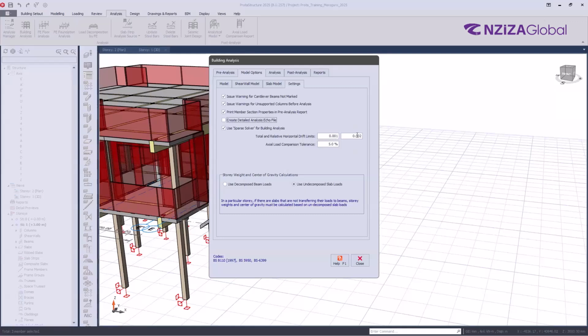If the drifts go beyond these values, you will have a warning. These are ratios: you take the horizontal side and divide by the vertical. Those values are exact. They are known.